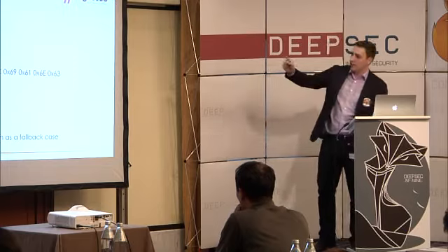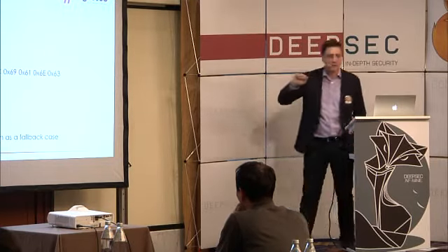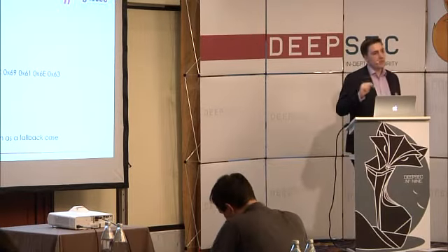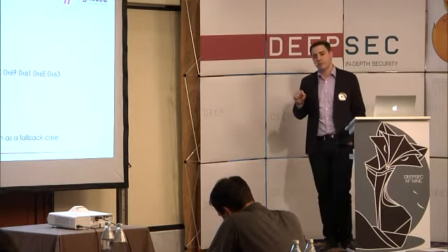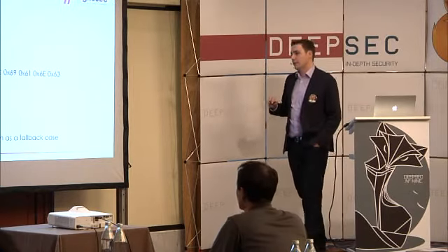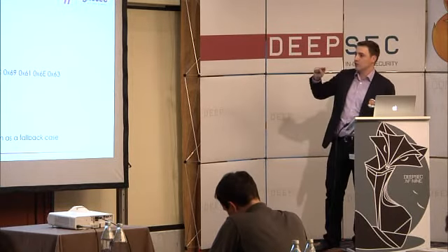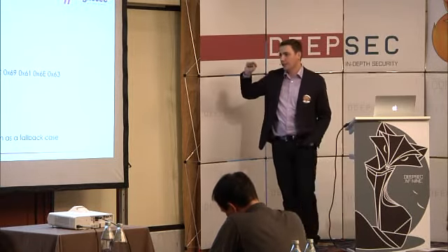But in combination with the second attribute, the default link key join, they require you to support this kind of encryption as a fallback. So every ZigBee device which is certified has to support a key exchange using the publicly known key.